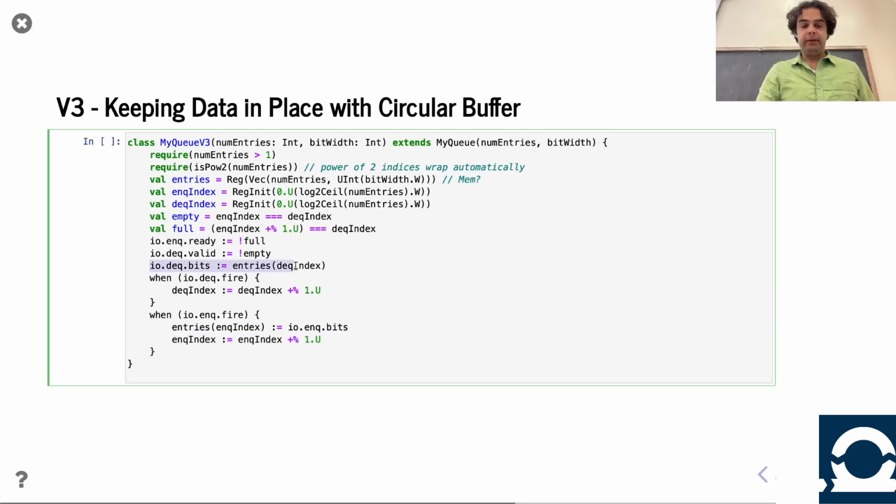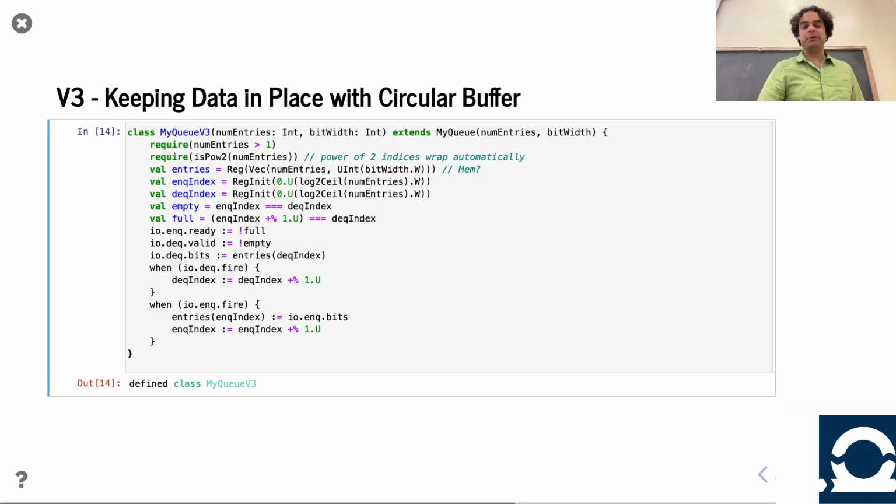Technically, I could pull this into this one statement for symmetry, and maybe that makes people happier. But there's not really a risk in leaving it outside. Reading a register is not damaging it. The reason we have to do this for NQ is we don't want to change the contents of the entries unless we're for sure doing it. But this read over here is non-destructive, so we can leave it on the outside for simplicity. A person who wants symmetry could probably sink it in there and see the cost for the hardware, and I think it's not much more. Questions?